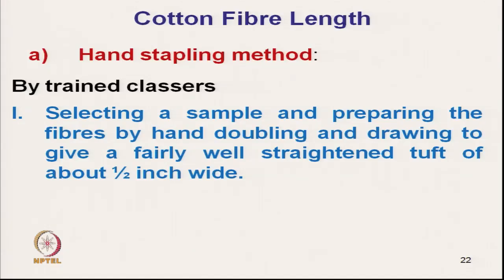The selection is important. We select a sample and prepare the fibers by hand doubling and drawing to give a fairly well straightened tuft of fiber about half inch.